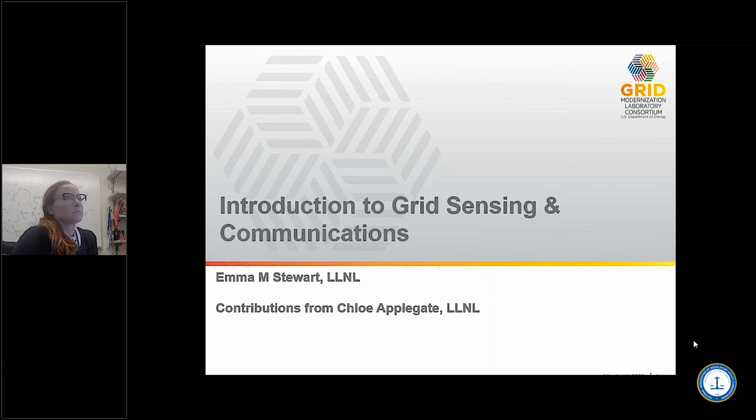Now, an auto transformer: for most power transformers, you have two independent coils and there's no electrical connection between them. It all goes through a magnetic flux. That's very good for providing electrical isolation, but it requires a larger device. An auto transformer is actually a single coil wound on itself.